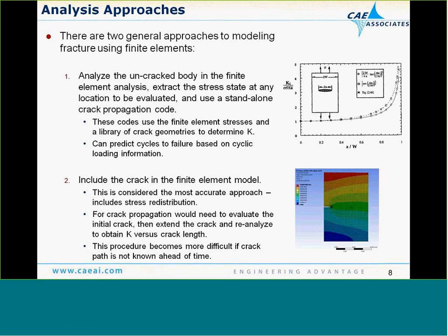Okay, so there's essentially two ways to approach this, and then I'm going to basically show you the second way. Just to be clear, when we do these types of analyses, one way that people do this is where they won't include the crack in their finite element analysis. They'll just run the finite element analysis to get the overall stress field for their particular geometry and loading. And then they'll take the local stress field at the region where a crack has either been inspected or is expected to be found, and they'll take those stresses and put those into a standalone fracture code. Some examples are that NASGRO is one, AFGRO.